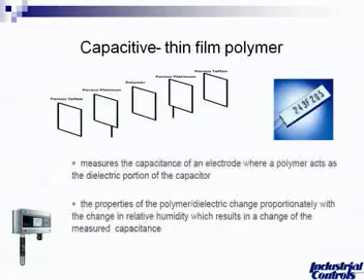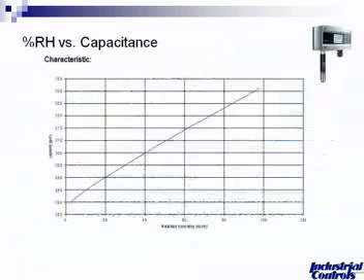This slide just sort of blows that out. In the center here, you have your polymer material surrounded by a sandwich of electrodes. In this case, it's porous platinum. And then oftentimes manufacturers will provide an additional layer of protection, and in this case it's a porous Teflon filter on the ends. All this together measures about 0.008 inches of thickness, so it's very thin, therefore very fast responding. It has airflow on both sides of it.